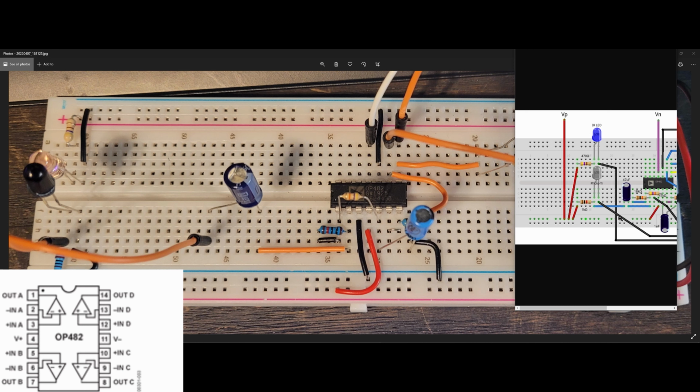So the only thing that's different is this blue wire right here. I've made it an orange wire and it's above this resistor. We could try debugging that to see if that makes any difference, and it goes straight into the capacitor right here. So with that, we have the rest of it pretty much the same. This wire is going to go to here, which is the second pin. We have our 47 kilo ohm resistor that goes from the first pin into the third from the last pin.